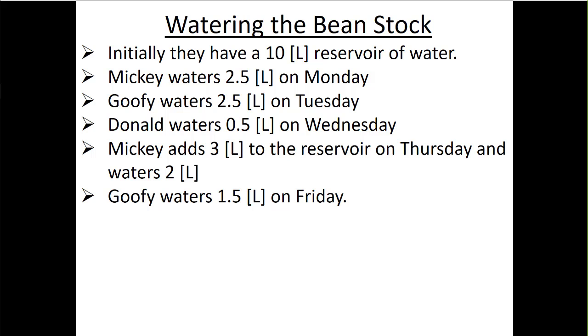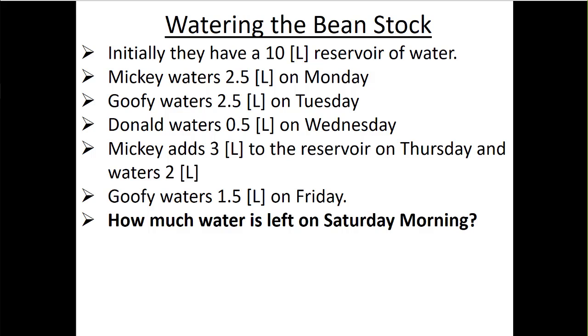So in order to answer this problem, we really need to know the density of water. But the first thing we would do here is we would say, oh, liquid water. Remember from before when we were talking about liquid water, we said it's actually incompressible, or very close to being incompressible, that the density of water doesn't change very much. So here we're going to assume that the density of the water is constant. Then if we wanted the mass of water that was coming in and going out, we would multiply the density by the volume change. Because the density is constant, it can just drop out of our equation because it's on both sides.